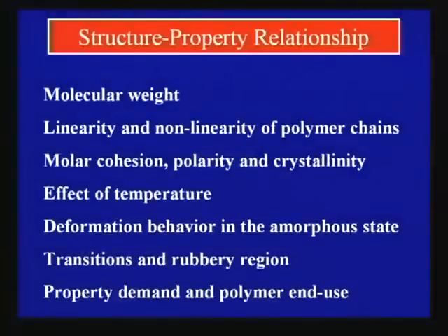Nylon is a polymer, a polyamide, the CONH functional group is there. Now, that CONH functional group is attacked by this acid, because the intermolecular forces of interaction in nylon occur through hydrogen bonding between CO and NH, CO, NH of one polymer with the other polymer. I will show. So, these are the things, the solubility concept and the polar mechanical properties. All these things are related to molar cohesion, polarity as well as crystallinity.